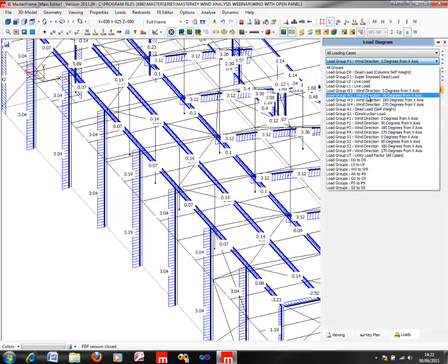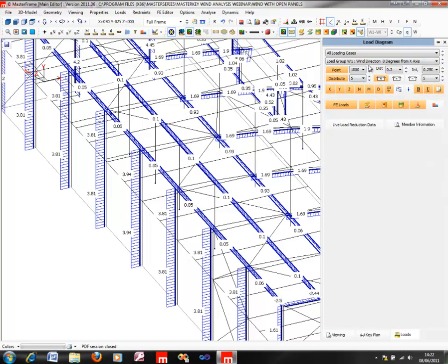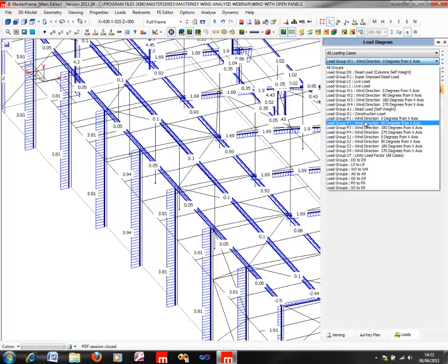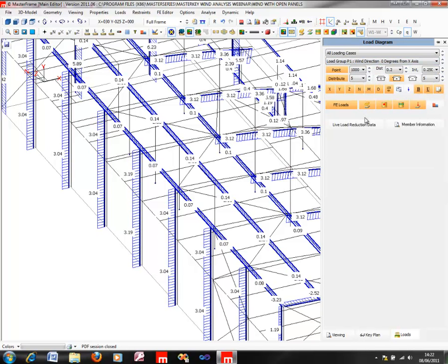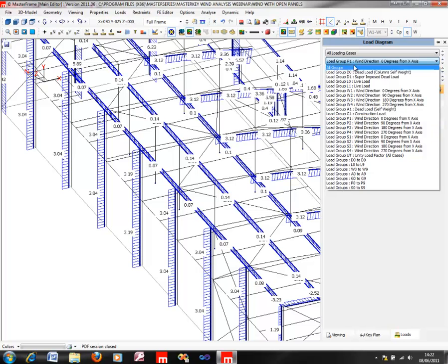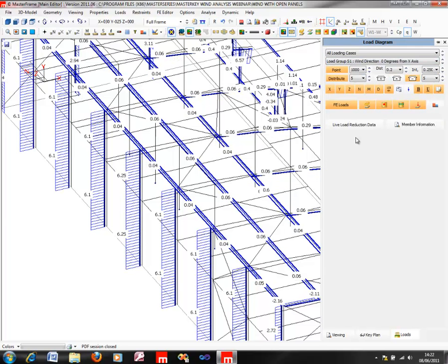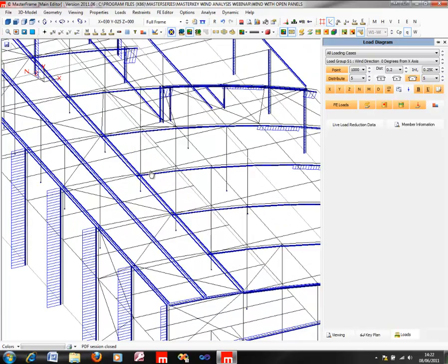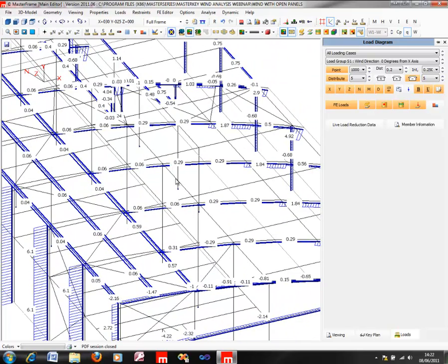We're actually looking at W1, but of course we can look at external wind with internal pressure, which is the P1. So internal pressure obviously is reducing those external values, whereas if we look at that with internal suction, we can see those values actually increasing because we've got external pressure with an internal suction giving you overall net increase, which obviously has the opposite effect, where we've got suction on the outside and then suction on the inside, cancelling certain aspects out.